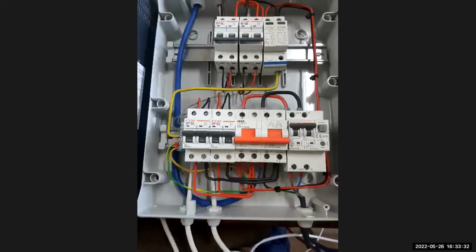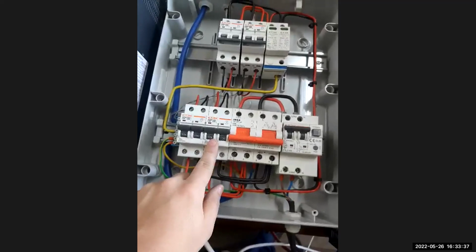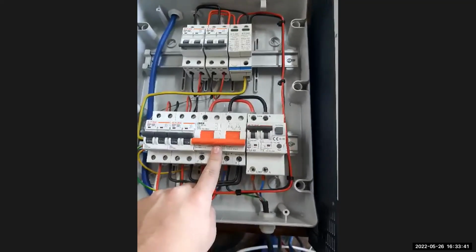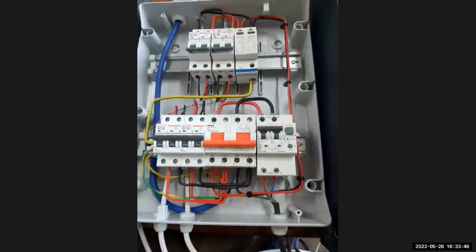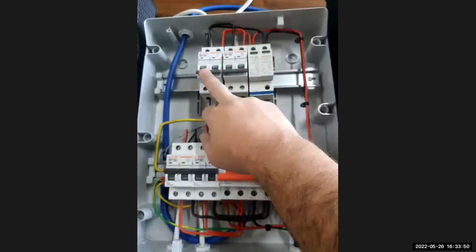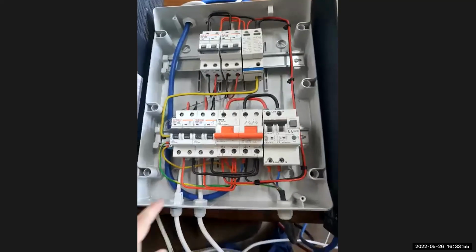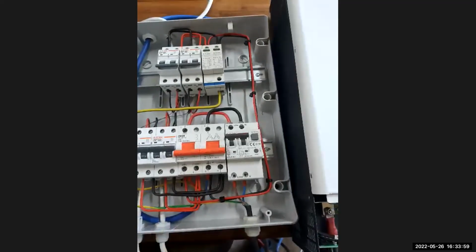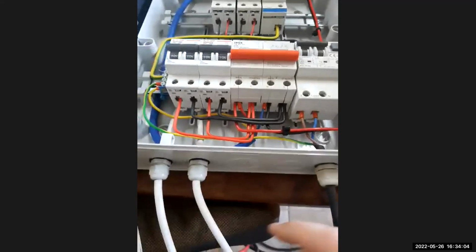Okay, on my parallel box, you'll see I have my two input breakers. Then I have my changeover switch and then an earth leakage to provide power to the loads. Then I have an SPD and my two input breakers. Now from this box, I like to do my paralleling work underneath my changeover switch because it has nice big holes to clamp all the wires nice and safely into it, as I have done here.